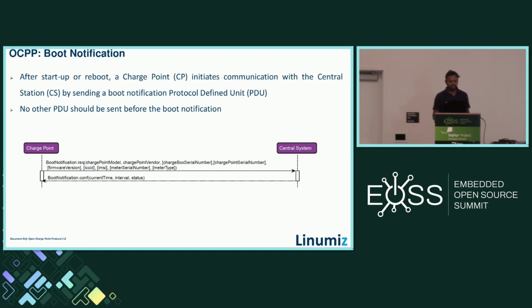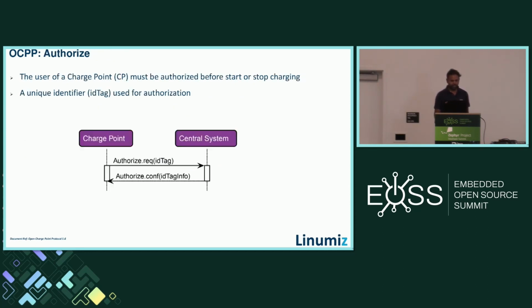The boot notification message carries information like the charge point model, charge point vendor ID, and the ICCID and IMSI. No other PDU message should be sent without the boot notification being acknowledged, or accepted, by the central system.